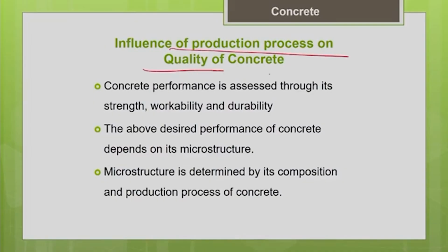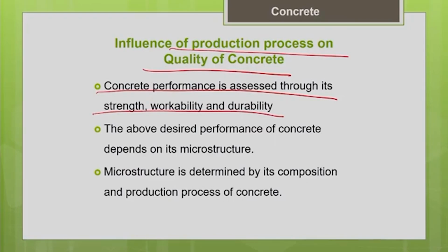One important thing to be noted is that the production process has a significant influence on the quality of your concrete. Generally we assess the quality or performance of the concrete in terms of its strength, workability and durability. You can get your desired performance provided your concrete has the desired microstructure. All the strength, durability, everything depends upon the microstructure of the concrete.